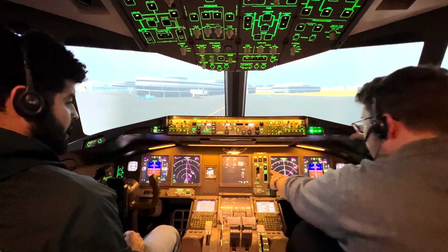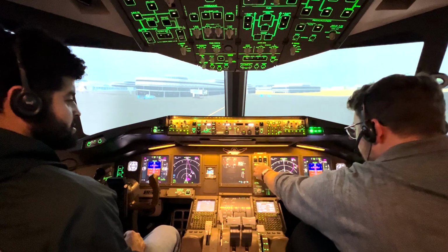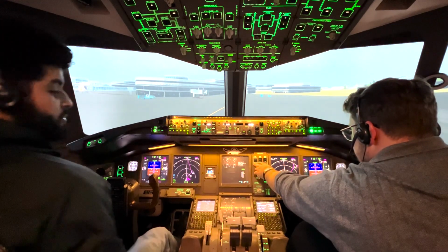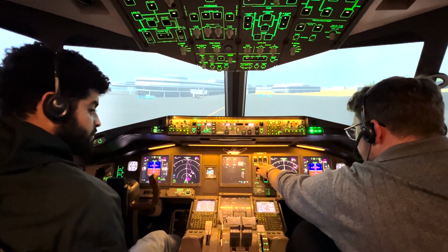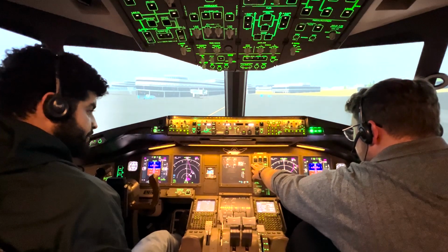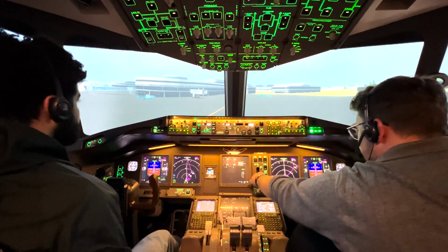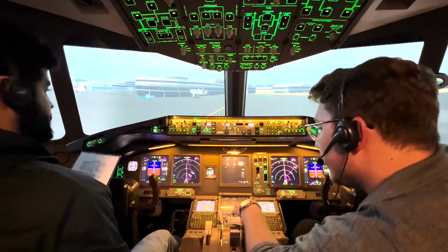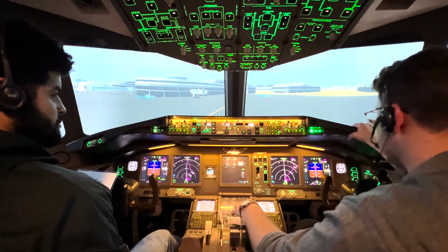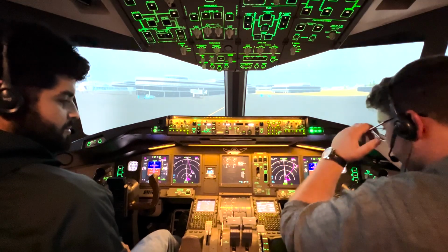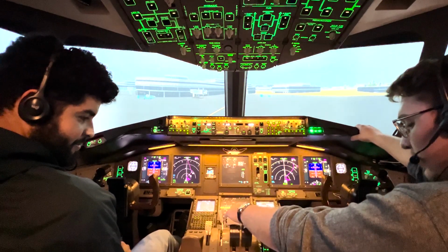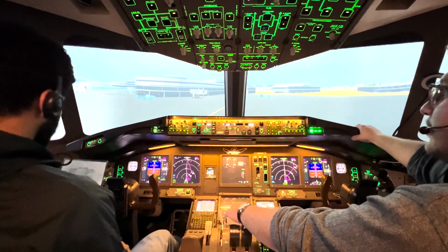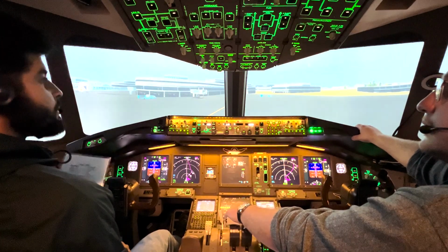Okay, so now we'll start off with taxiing here. And we'll make sure our terrain override is not on. And we'll also make sure our flap override is off. Gear override is off. GS inhibit is off. Heading reference normal. MFD, nav, FFC auto. Okay. So, what was it that I was going to do now? Taxi lights are on. Yeah, we're good to go.